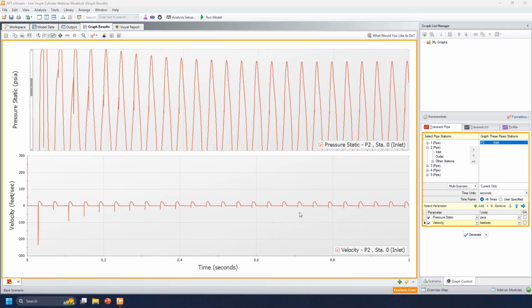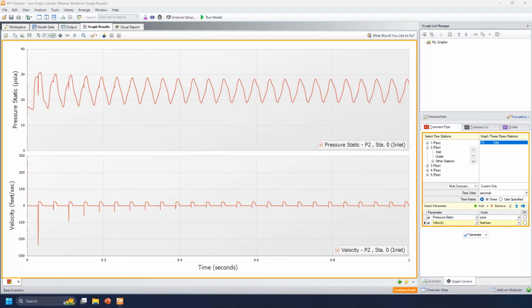That's normal. However, if the change is too large to the point where it's affecting your force results in the system or your frequency results, one thing that you can do is adjust the discharge crank angle if it's causing issues on the discharge side, or the suction crank or the suction valve angles if it's causing issues on the suction side of the system. But in this case, it is all looking okay.